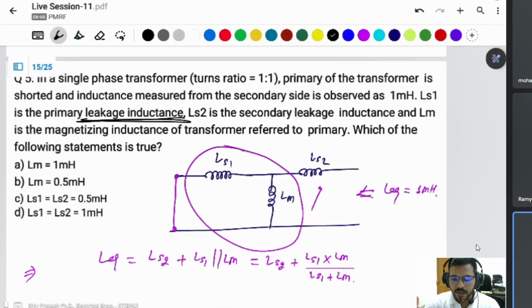If you take a winding and wind it on a core, then there is an inductance of this core with this winding. In a transformer, there is a leakage inductance which will not transfer to the secondary side. It means this will not link to the secondary side, it links only the primary side, the leakage inductance. Then there is the primary inductance, which is a different thing.